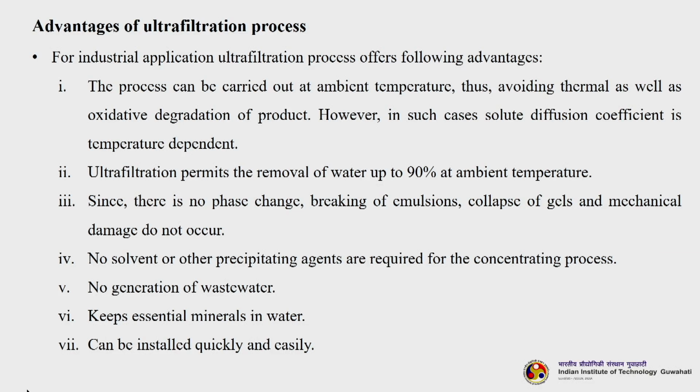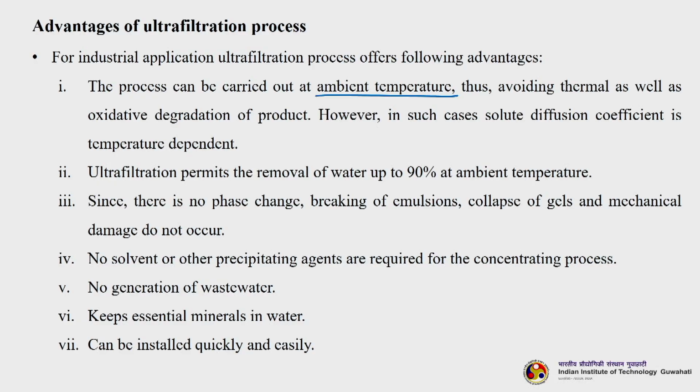So, let us understand the different advantages of ultrafiltration processes. For industrial application, ultrafiltration processes offer the following advantages. The first one is that the process can be carried out at ambient temperature, thus avoiding thermal as well as oxidative degradation of products. So, no thermal requirement is there here. However, in such cases solute diffusion coefficient is temperature dependent. The second thing is that ultrafiltration permits the removal of water up to 90% at ambient temperature, since there is no phase change occurring.